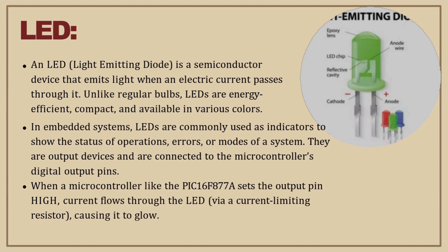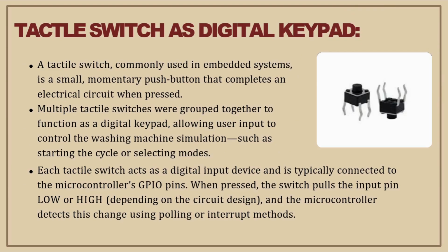Now let's move to the next peripheral, tactile switch as digital keypad. A tactile switch commonly used in embedded systems is a small momentary push button that completes an electrical circuit when pressed. Multiple tactile switches were grouped together to function as a digital keypad, allowing user input to control the washing machine simulation, such as starting the cycle or selecting modes. Each tactile switch acts as a digital input device and is typically connected to the microcontroller's GPIO pins, general purpose input output pins. When pressed, the switch pulls the input pin low or high, and the microcontroller detects this change using polling or interrupt methods.